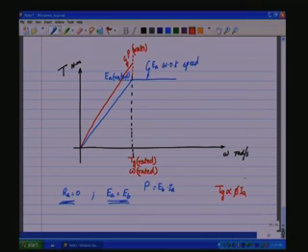We are not going to change anything on the armature side, because armature voltage has now reached its maximum. So, the only other parameter to control is phi, and phi you can't increase more, because already the voltage is the maximum. Any increase in the voltage will saturate. So, therefore, you have to only decrease the flux. So, we decrease the flux, which means TG starts reducing. So, you can still go beyond the rated speed by reducing the torque.